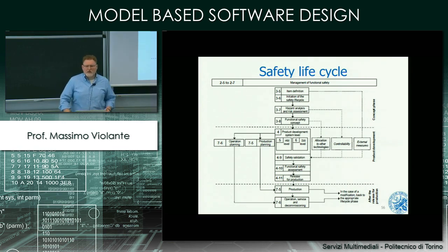Think about the ABS. The ABS is able to work in different modes. There is the full mode, where the ABS is able to measure the speed of the wheels by reading through 4 independent sensors the rotational speed of each of them. Then based on this, and knowing the speed of the vehicle as received from another system inside the vehicle, it is able to understand whether there is a wheel that is losing friction.